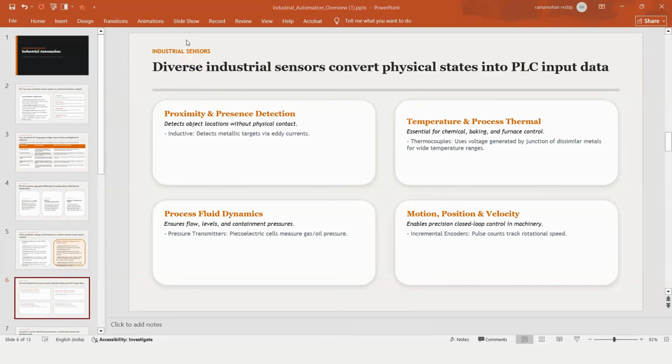I think it's kind of, I don't want to say vision sensor. I don't know, but okay, kind of a motion sensor we can call it. If some motion is happening, then it triggers a signal. If no motion, no signal. And you can keep a delay of 5 seconds or 10 seconds or 1 minute. If for 1 minute there is no motion in that particular room, it triggers a signal to the switch controller. And the controller either turns the light on or off, or the fan on or off. That depends on the controller.